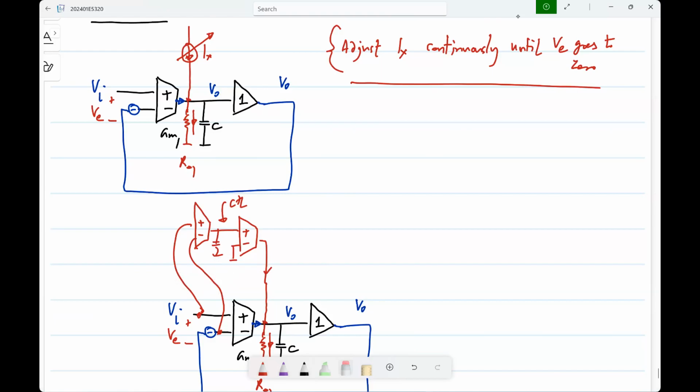Is that okay? So you take that error voltage, you integrate it, and based on that integral, you have another current source feeding to the output. So if this works ideally, then the whole process will stop when this voltage is steady, right? Again, for all these things, it's easiest to imagine a DC steady state. Vi is DC, Vo is DC. Finally, everywhere you should have DC.